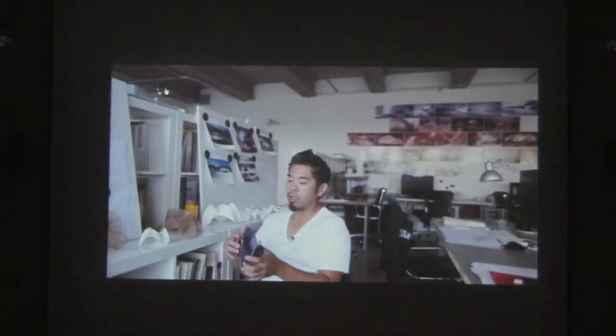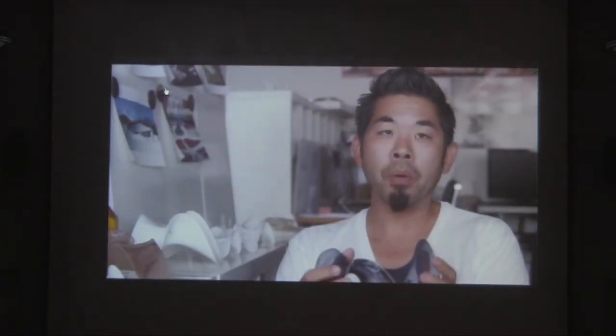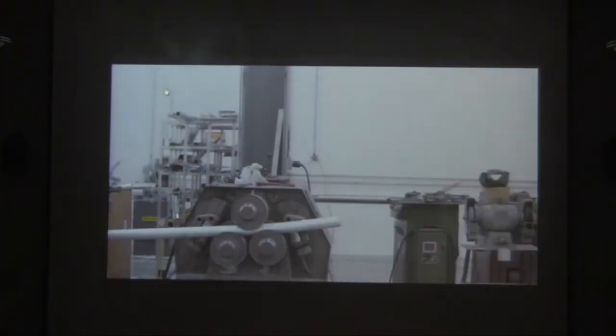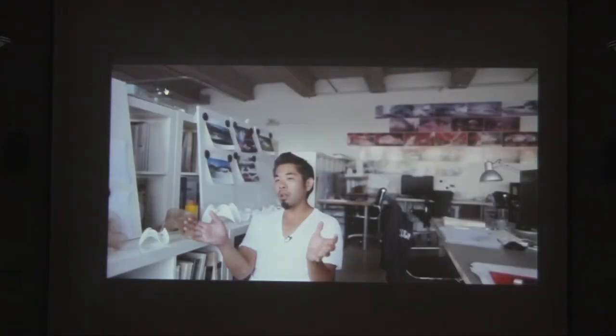So the original idea was that the structure would wrap up and bundle into a little package, like a laundry hamper, and just pop over, which would have put us well out of budget. So we ended up moving towards a CNC bent aluminum frame, which is slightly outside of the final shape it's going to take. It gets tensioned into position by the skin.